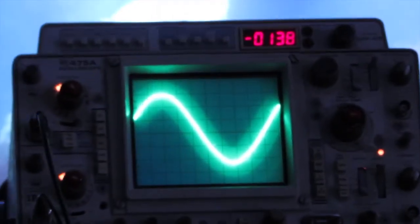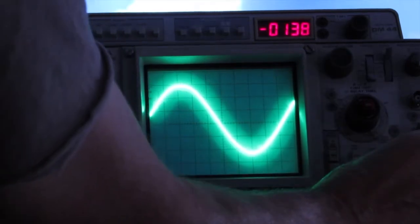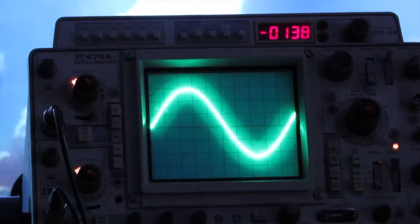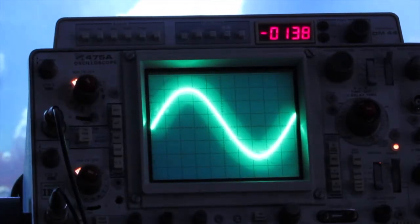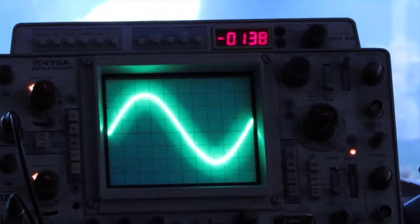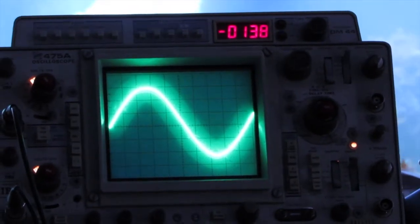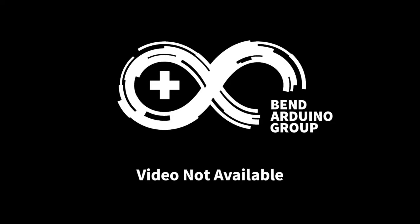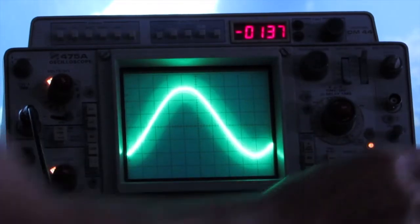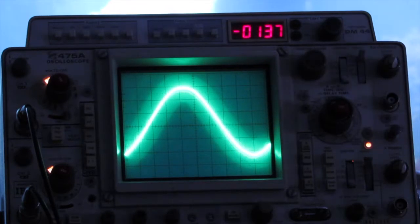Now, alternately, if I go to center, the trigger level I now have set at the center grid line, and so the sine wave is starting right at the center of its sweep, and I can go below and start from a negative voltage, like minus 1 volt.